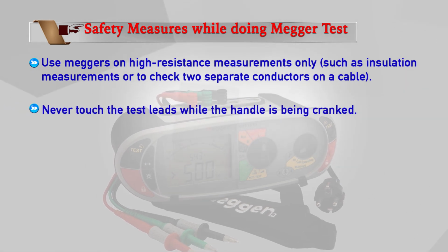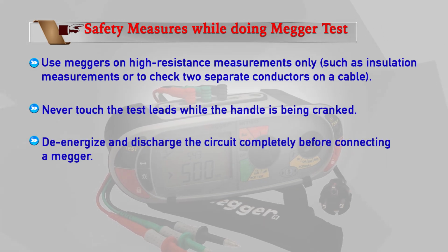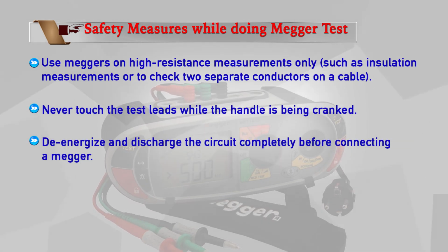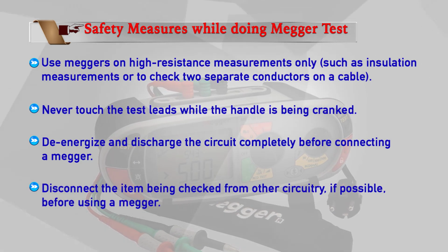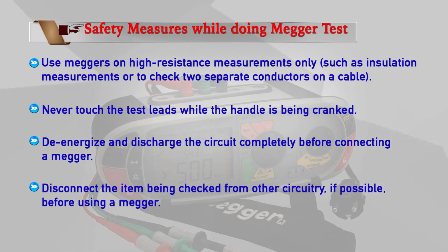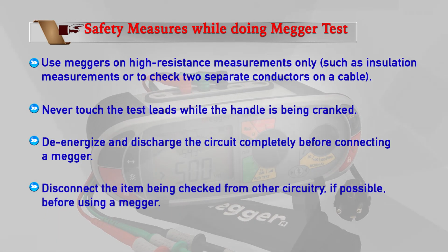Never touch the test lead while the handle is being cranked. De-energize and discharge the circuit completely before connecting the measure. Disconnect the item being checked from other circuitry if possible before using the measure.